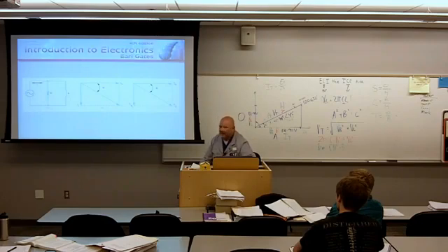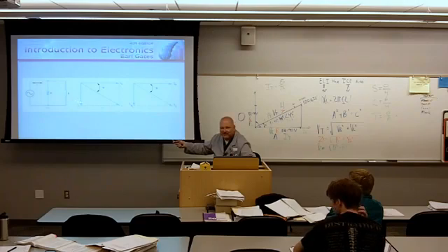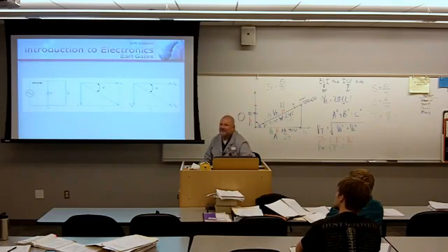Classic example on a professional exam. You take your CET exam or your FCC exam, they'll give you this circuit here and say you've got 2 amps flowing through your resistor and 2 amps flowing through your inductor. What's total circuit current? Answer A will be 4 amps. Answer A is wrong. You know it's going to be more than 2, but less than 4 because it's the vectorial sum that you're actually calculating out. Does that make sense?